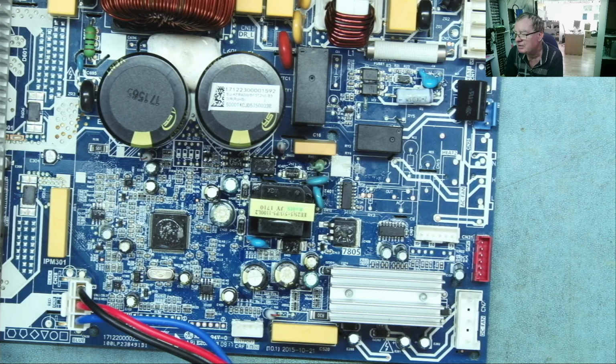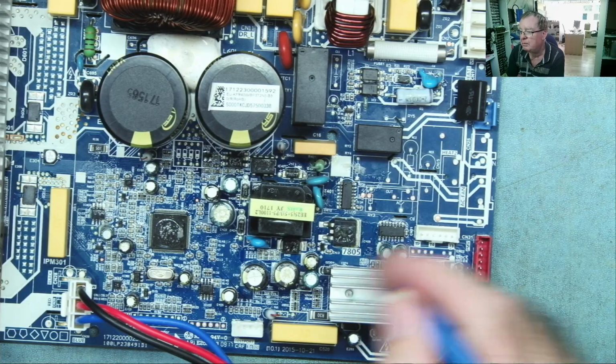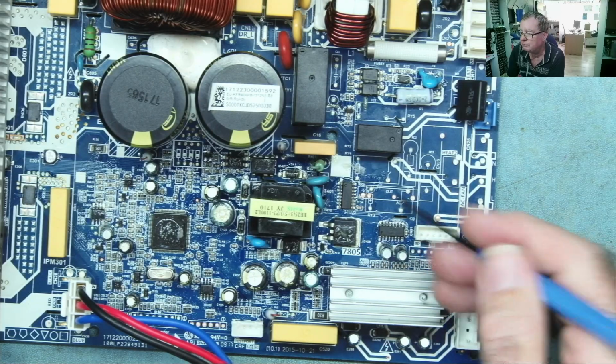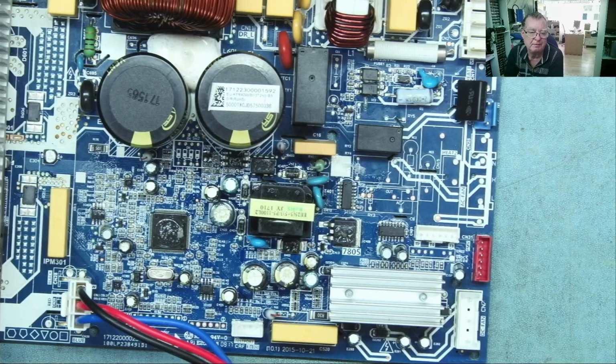You can't necessarily say what they will read, but they should all read the same as each other, depending of course what may be plugged in here. But in a lot of cases you can probably find one which has a defective driver in it. Bear in mind these things will normally have 4, 7, 8 drivers in one package, so the symmetry means there's a number of the same and you can make a comparison. So things that face the outside world, inputs, outputs, buffers, latches, drivers, these are another common cause of failure.